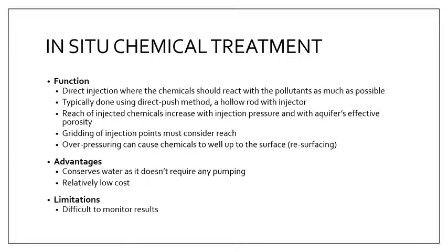Okay, now the issue or the limitation here is it's quite difficult to monitor the results of an in situ chemical treatment. First is because you have to put monitoring wells, and second is there's actually a lot of natural processes that will attenuate your contaminants. So you have your dispersion, you have your diffusion or the spreading of your contaminants, which causes them to dilute.